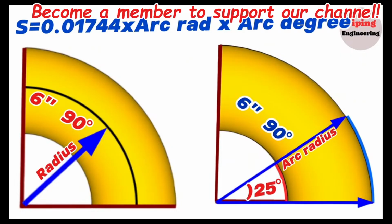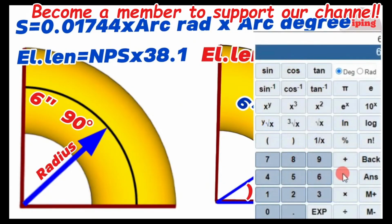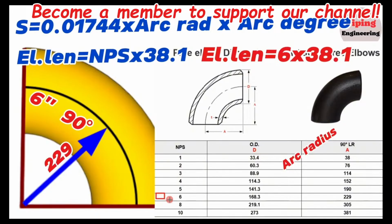The formula for calculating the length of 90-degree long radius elbows is as follows. Elbow length in millimeters equals nominal pipe size multiplied by 38.1. So, the 6-inch 90-degree elbow length will be 6 multiplied by 38.1. Using the calculator, 38.1 multiplied by 6 equals 229 millimeters. Let's check this result with a dimension chart of 90-degree long radius elbows. We can see in the chart, nominal pipe size 6-inch long radius elbow outside diameter is 168.3 millimeters and center to end dimension radius is 229 millimeters.